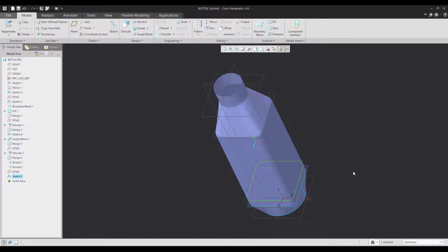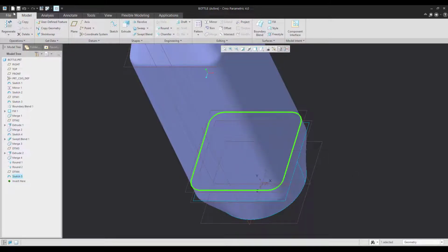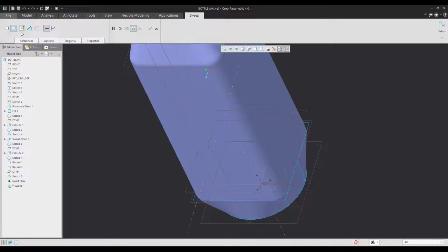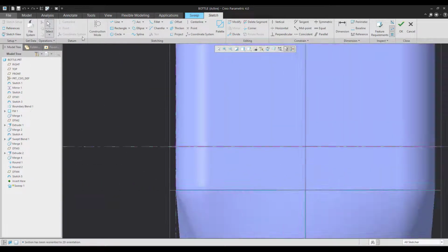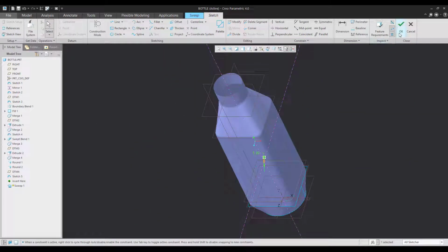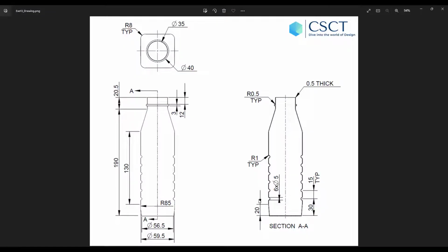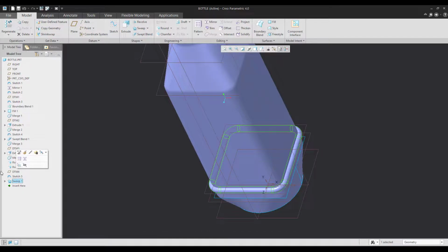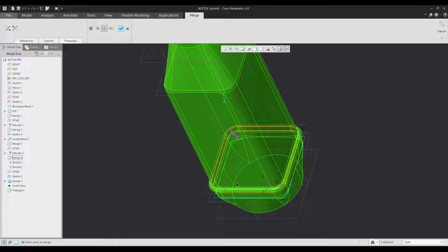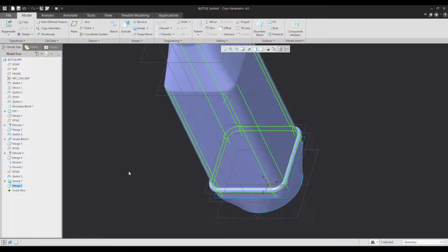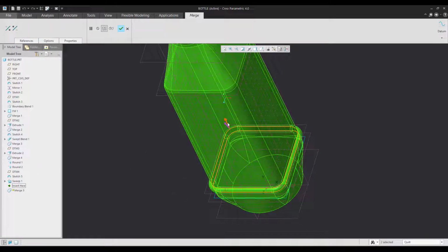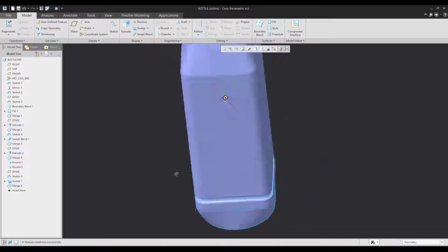This is my sketch. Now, I'll use the sweep command. Say it's a surface, start making a sketch, and then we all know that the sketch is of a circle which is of 5 diameter, and say okay. It creates a surface passing through the profile which we have sketched. Now, the groove whatever you're seeing is actually removing a certain amount of material of the existing body. So let me try to create a merge in between these two and keep whatever I require and remove whatever is not necessary. I do not require this side, so I'll just flip it towards the other side and you can see the groove.